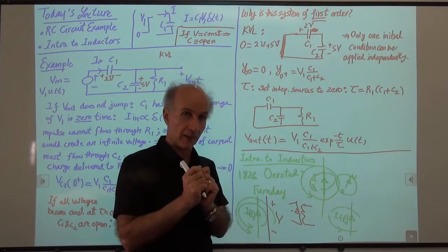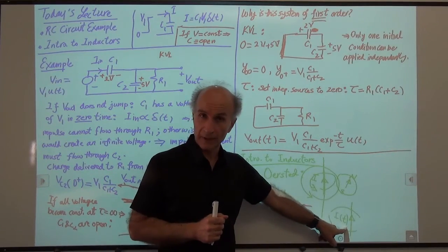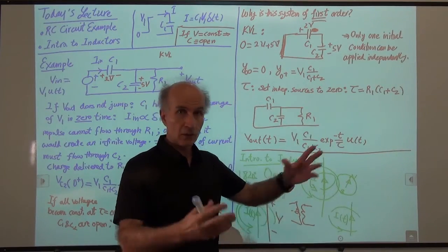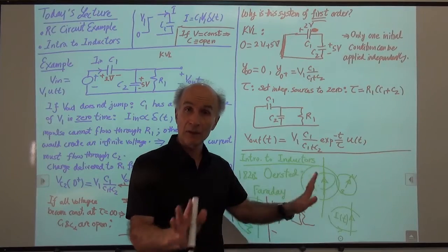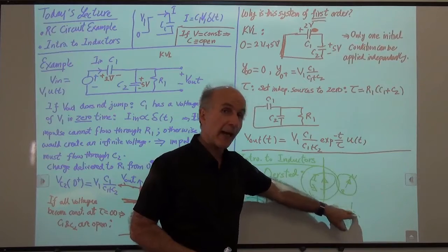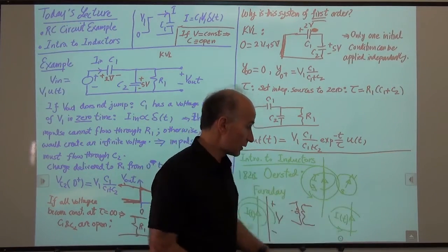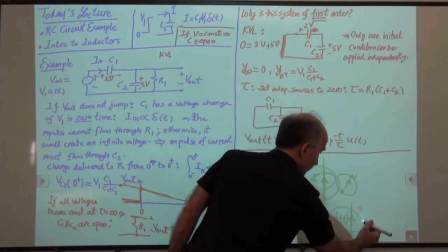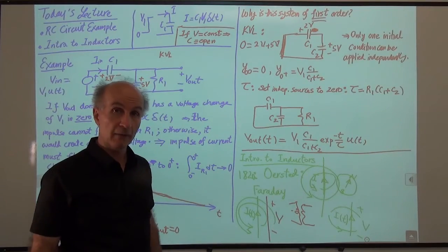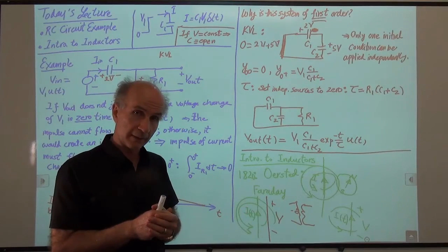All right, so let's make sure we understand this. If the current doesn't change with time, the magnetic field doesn't change with time, and there's no voltage here. It's just a simple piece of wire, ideal piece of wire. We have a magnetic field, everyone's happy, nothing is changing. But if the current is changing with time, and as a result, the magnetic field is changing with time, then this wire develops its own voltage here, some voltage V. Okay, even though it seems like an ideal wire. So it definitely does not satisfy Ohm's law.